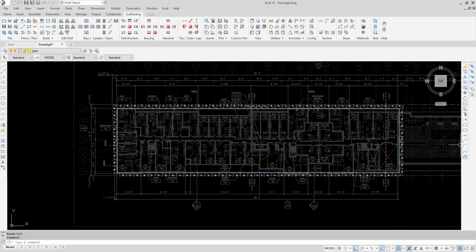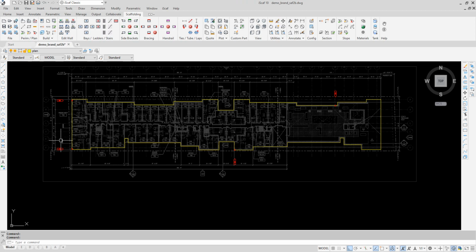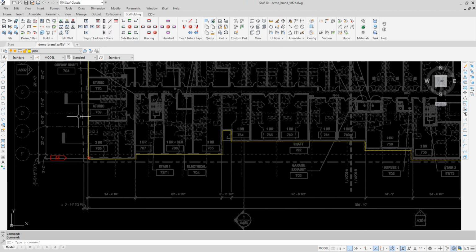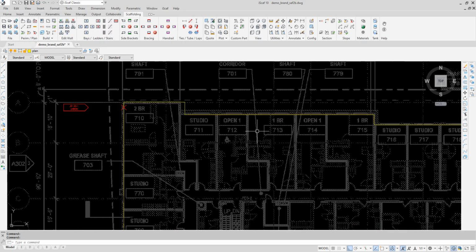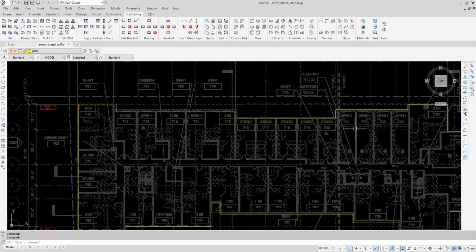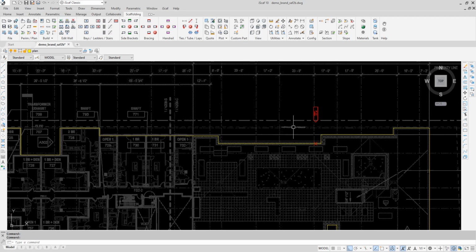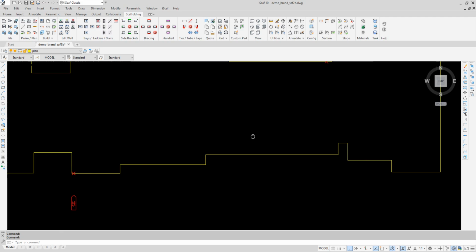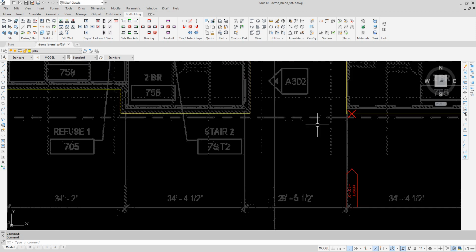So let's jump ahead now. We've actually performed a full trace of that building perimeter, and we've also added sloping ground. You can refer to our other tutorials in relation to sloping ground, but we have a slope tag of 0. We have a slope tag of -10 at this point, so it slopes from 0 to -10. Over here, we have another tag at -10, and we slope all the way back to -15 here, and from -15 we go back to 0.